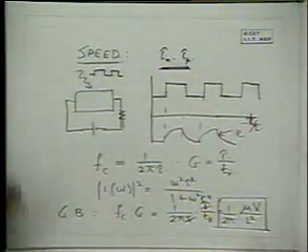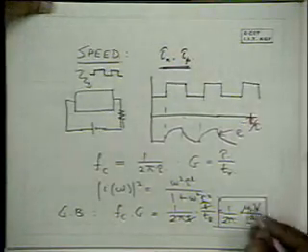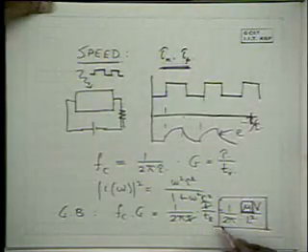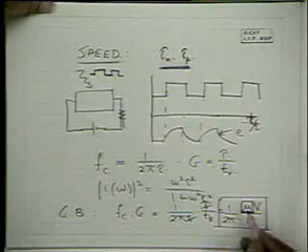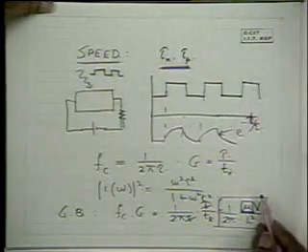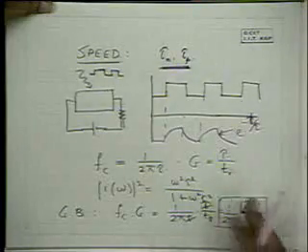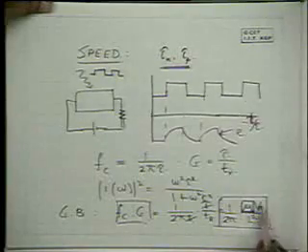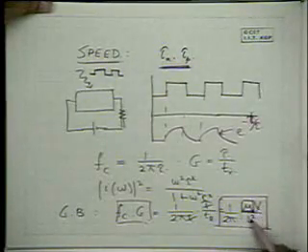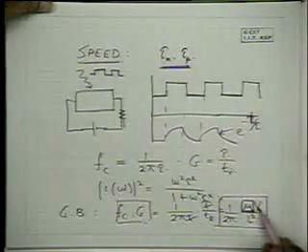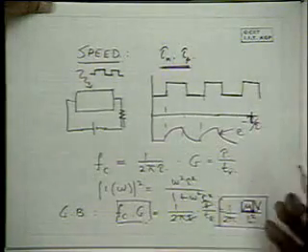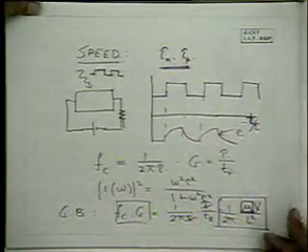that the gain bandwidth product of a photoconductor is determined by mobility. The lifetime does not come in here. You can get higher gain by having higher lifetime, but then the speed is slower. So the gain bandwidth product depends upon mu, and of course you can get a high value by reducing L or increasing V, until of course there's a limit. At high V, not only do you get space charge limited current, at still higher voltages you will get breakdown. So there's a limit to V then.